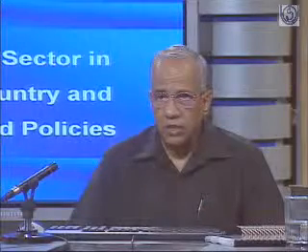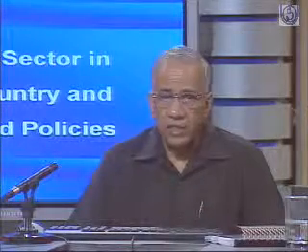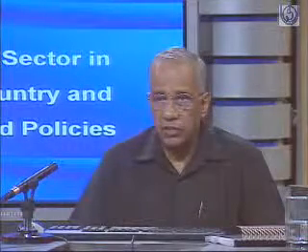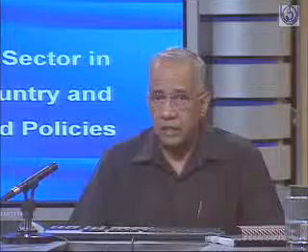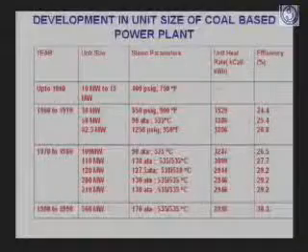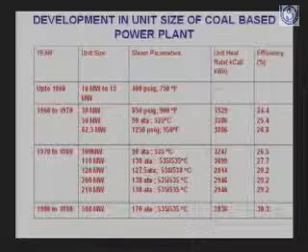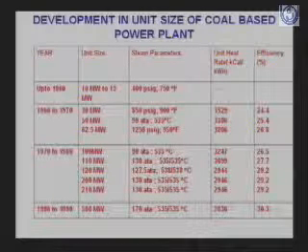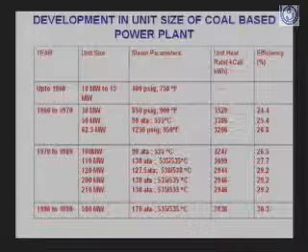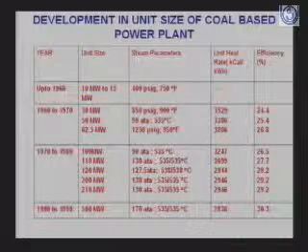It depends on the atmospheric temperature, the temperature of cooling water which exists at a particular site. This cooling water is used for cooling in the condenser where the steam condenses, and that is the temperature of the heat sink. Therefore these two values, the temperature of heat addition and the temperature of rejection, are the boundary conditions limiting the efficiency of a steam cycle.